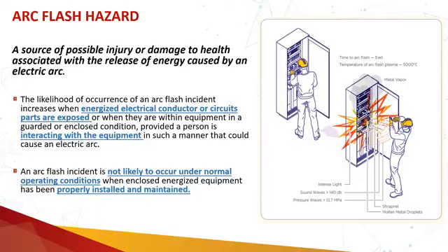This responsibility comes under NEC and NFPA 70B. The installation requirement is with NEC, which is NFPA 70. The maintenance requirement is with NFPA 70B. So if NFPA 70B and NEC have already been implemented, the equipment on which you are not performing any job should not cause you any issues. Any question on this slide, or any further clarification required?